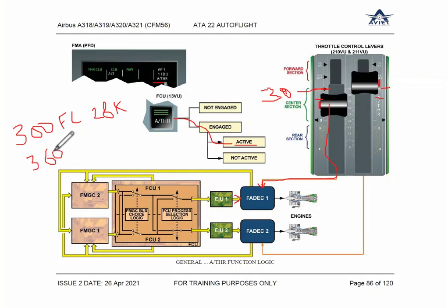Now, the pilot has to fly to flight level 360, meaning 36,000 feet. So what happens? He will climb, correct? More power. The aircraft will climb, so you need more power. Very good. Now let us say it might need 31K power. It might need 31,000 pound power to reach flight level 360.